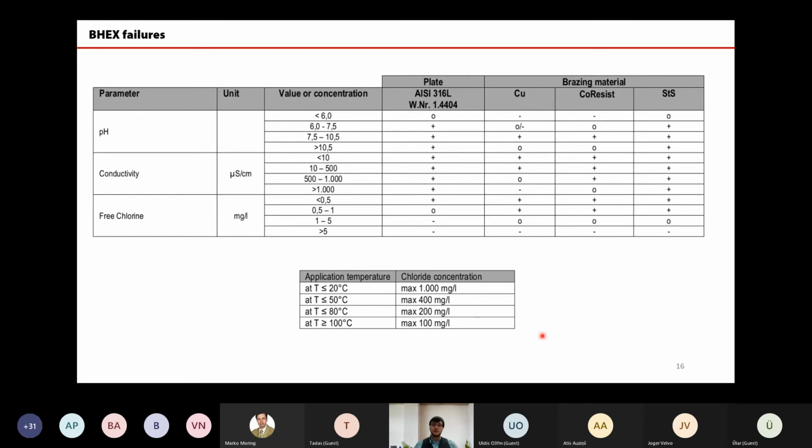On top of this, you need to properly calculate capacity for your domestic hot water application, not over-dimensioning it, because in modern systems, we see the real domestic hot water need is dropping to half compared to what some norms and regulations are advising us. And here, I'm not even touching the whole topic of how to properly select the valve, because that requires another webinar. So what I'm addressing to you is just select the valve using proper flow rate on the primary side.